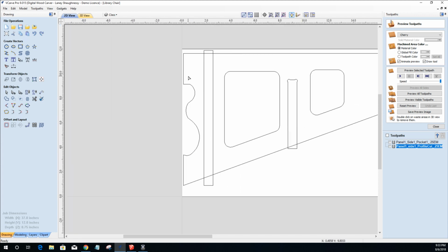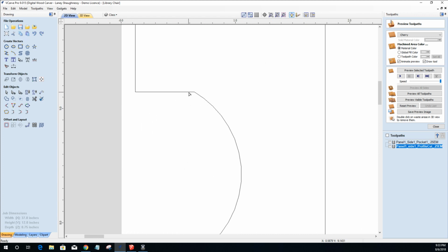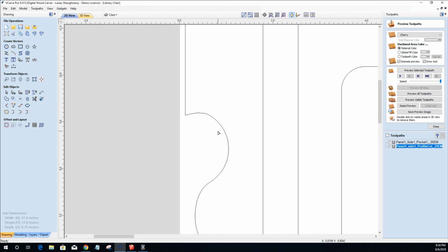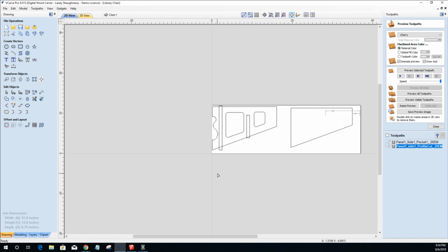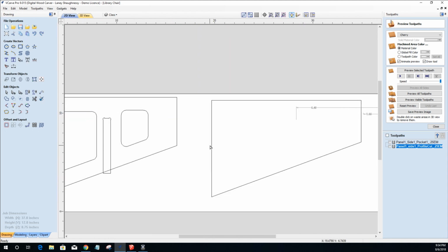And you can create that nice little transition if you don't want it so straight line-ish. Right click and Bezier curve. Let's pull this one out and around so it's in line with that arc, and then just bring this, smooth it out there. Okay, create that nice little transition. So that's one option.